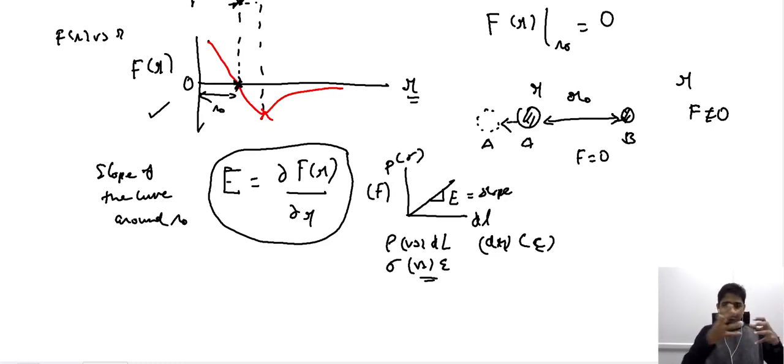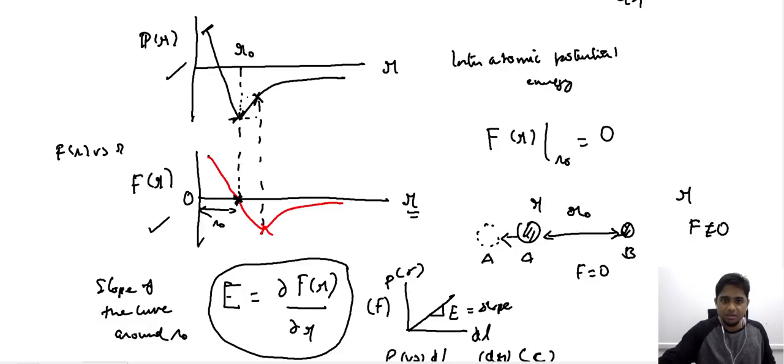So there are conceptual relations that we can make from understanding the mechanical behavior from the atomistic scale to that of the macroscopic scale. These conceptual understandings include being able to state why, when you impose a uniaxial tensile loading and there is a longitudinal increase in the dimension, the material goes back to its original state. It can be explained by both the interatomic potential and also the interatomic force.